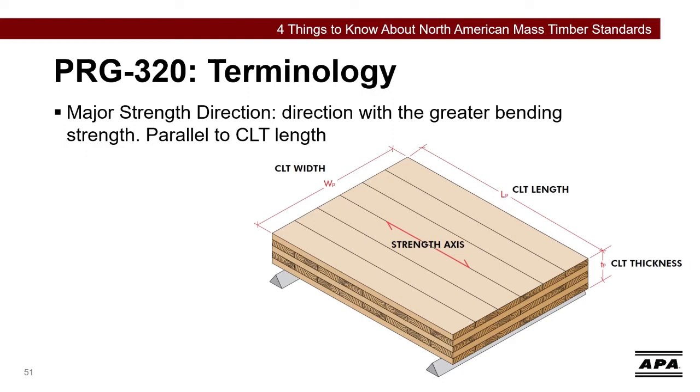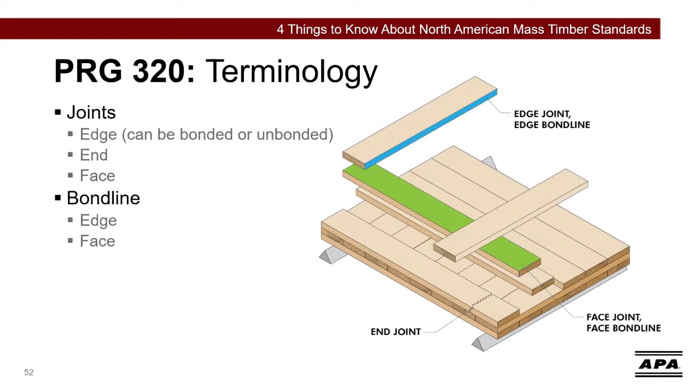Wood fibers in any decorative or architectural layer are not considered structural and not an indicator of the major strength direction of the CLT panel. For some unbalanced layups, the major strength direction may be difficult to define or determine without a model calculation. See Appendix X3, Section 3 for guidance on developing an unbalanced CLT model.